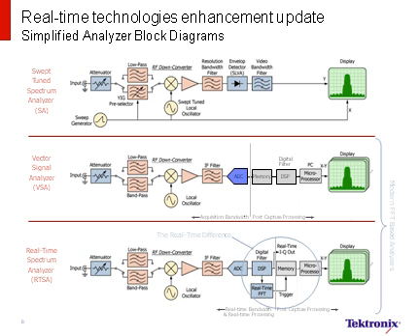In the bottom example of a real-time spectrum analyzer, many of the elements of the vector signal analyzer are similar. However, the real difference is the parallel path and the real-time processing engine that provides for real-time functionality and unique capabilities with regards to display, triggering, and analysis of signals.